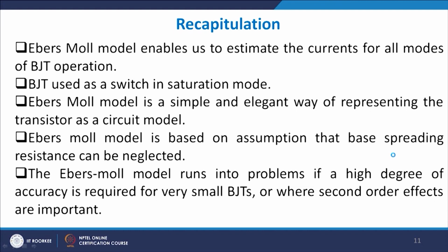In the active region, it will be very high and remain high for quite a long time, unless an external force is pulling the node down. Cutoff is the region where the effective current is approximately 0. Please keep in mind that it is the effective resistance that goes to 0; the real resistance might not even go to 0 at any point of time.